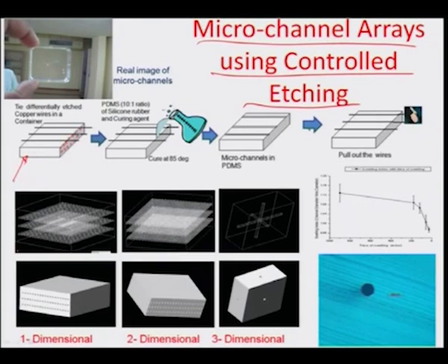And then once these are well knitted, these wires are replicated. So, you pour liquid PDMS over these wires, and then you can cure the PDMS, so that the PDMS forms a hard, solid, rubbery membrane, and then you can swell the PDMS matrix, so that you can individually pull the wires out, and that results in your microchannels.